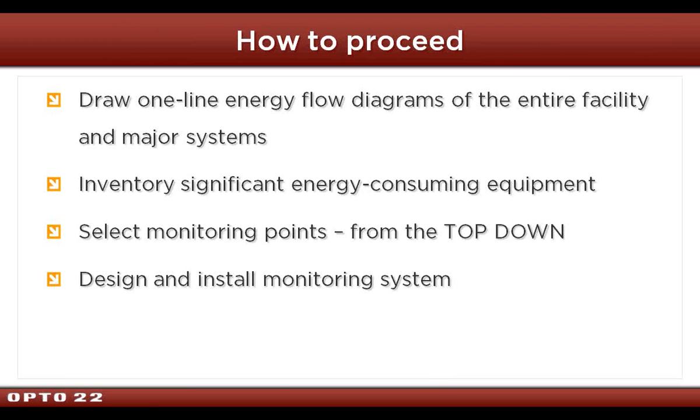Okay. Well, so you assume you want to go into a building and gather information on where the energy is going. How do you do it? What's involved in terms of design and hardware? And this is basically, you think of it as a financial budgeting system. I mean, it's where's the money going? What's important? And so the first thing we do is we draw a one-line energy flow diagram of the entire facility.